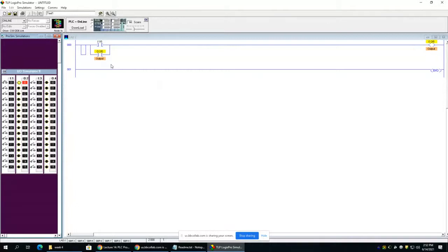So normally what we do, when I want to program it off, what I want to use is a normally closed button. Your start-stop sequence, you use a normally open button to start it and a normally closed button to stop it. And that is an OSHA rule. If you guys know OSHA, that's an OSHA rule that you have to use a normally closed. The reason is if you have to disable something, it's easier to break the power if it's to open the switch up than it is to try to close it.